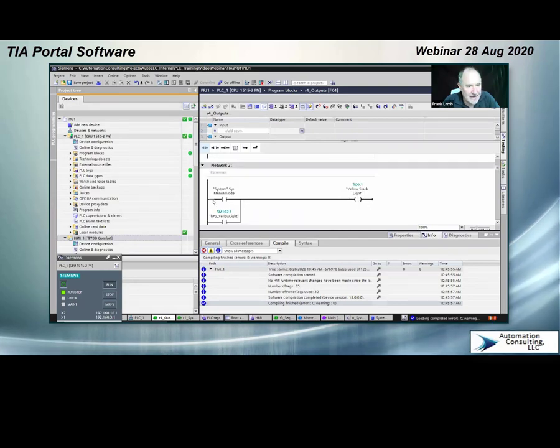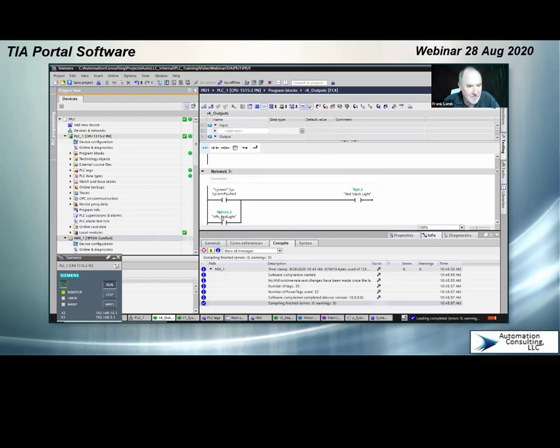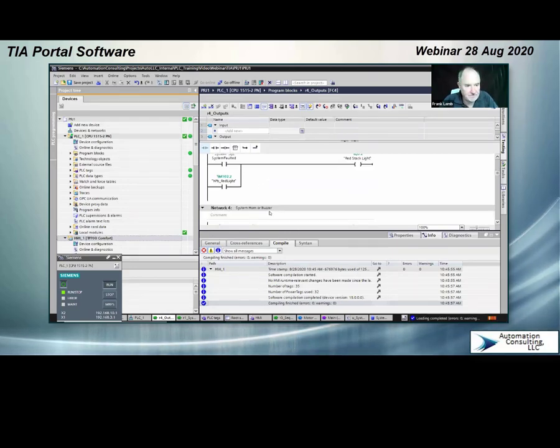Very simple here. Manual mode turns on the yellow stack light. Also, the push button turns on the yellow stack light. So that's how I'm doing that. Same thing with the red light. And once again, all these are running because I called the outputs routine with my OB1.